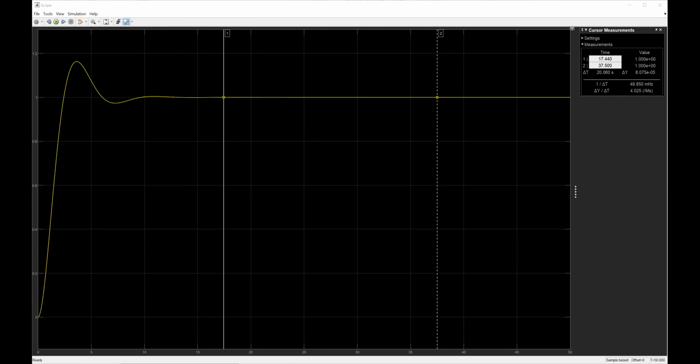But I just want to show you what the steady state error is. What is the response at the steady state? Response at the steady state is 1. What is the forcing function magnitude? Which is 1. So the steady state error in this case is actually 0. So this is called the time domain specification.